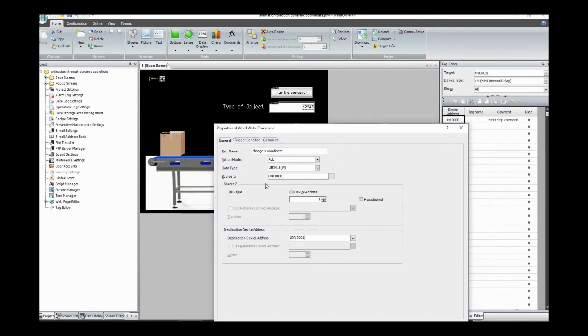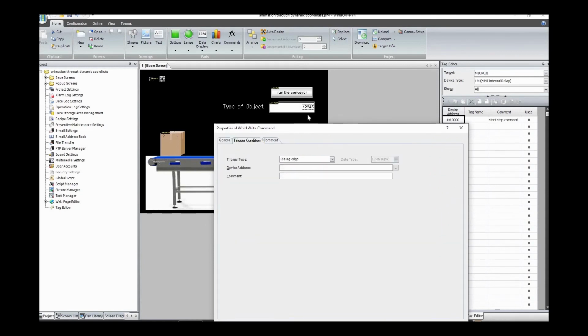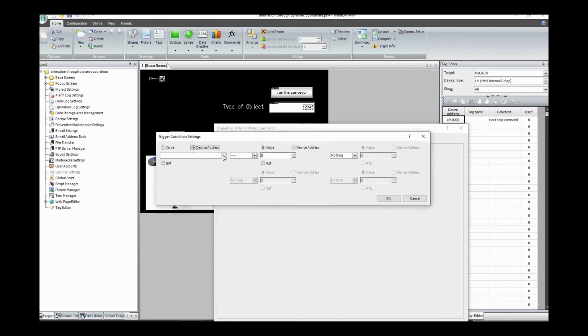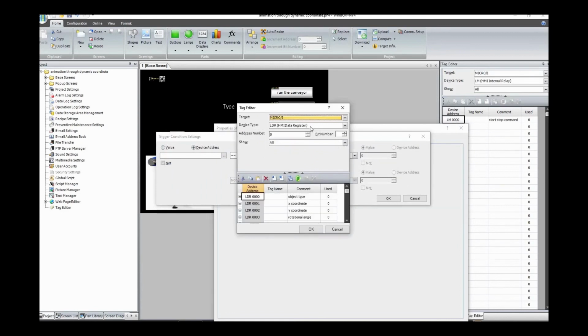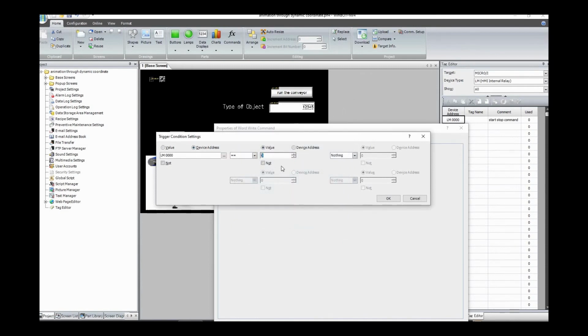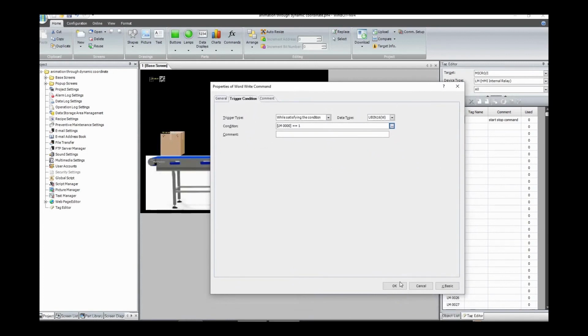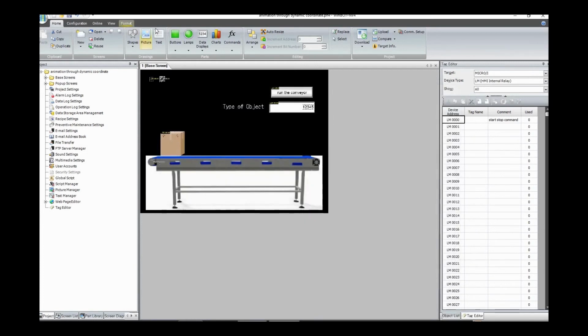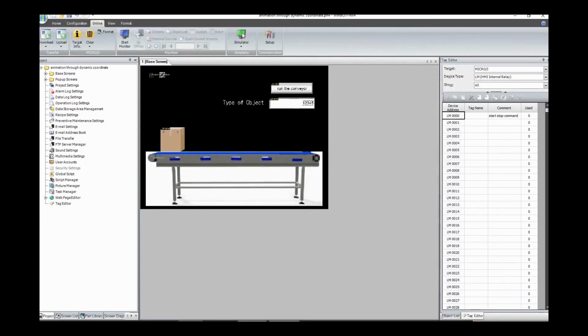And when should we do this summation? It's when the button is pressed. So let's set the condition. While satisfying the condition, when this button is pressed, LM0 is going to turn on. LM0 equal to 1. We should do this summation. Let's do a simulation to see how it works.